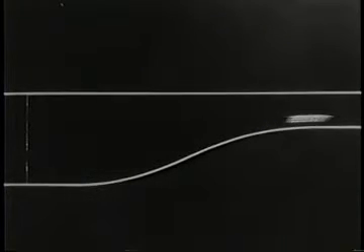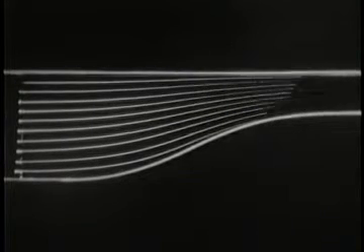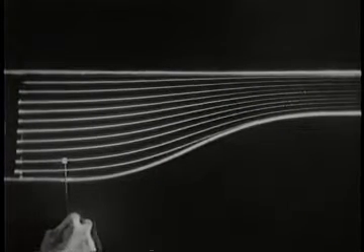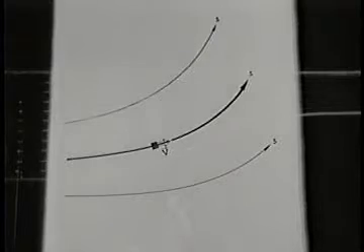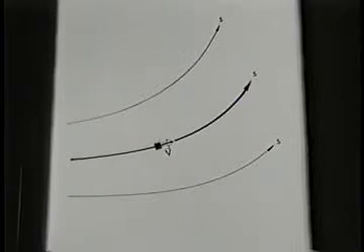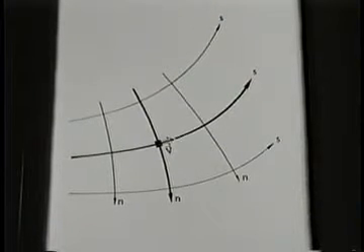The velocity increase in the contraction is coupled to the pressure decrease by Newton's law of motion. Let's see how. Here, the bubbles mark many streamlines. Let's imagine that this is a typical fluid particle. For thinking physically about the problem, it is helpful to use the streamlines S and the normal trajectories N as curvilinear coordinates. First, let's look at the forces and accelerations along S for the typical fluid particle moving with speed v along S.